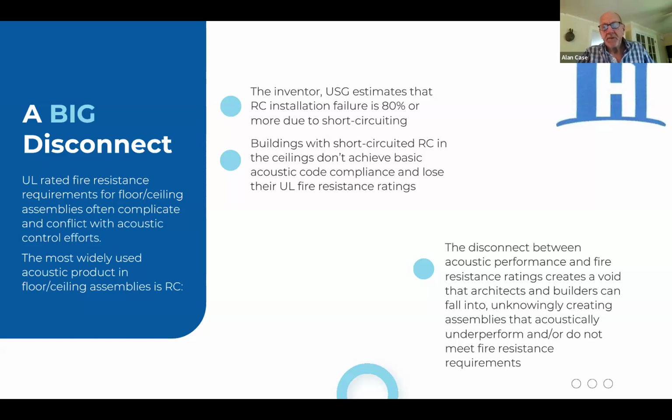And that's all they publish. So the architect will look at it and say, oh, this says it conforms to UL 521 or 528, when in fact, if they actually read UL 521, 528 and looked at the spacing, they would realize that it has absolutely no relationship to the acoustic representation from the manufacturer. It only shows itself in field testing.